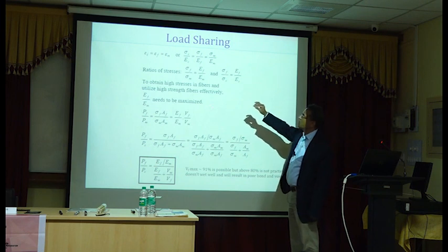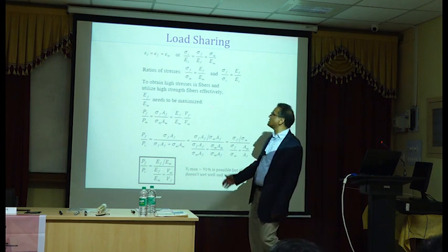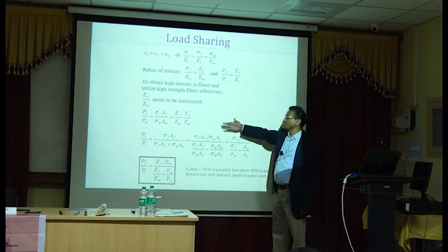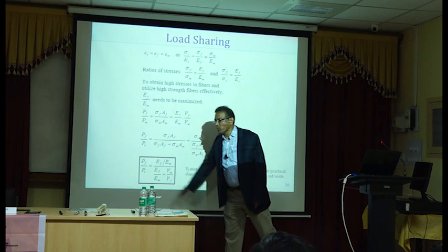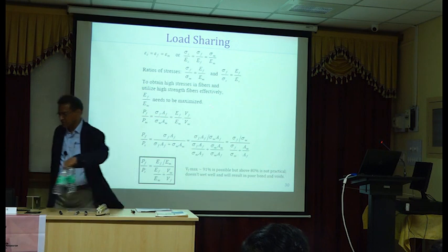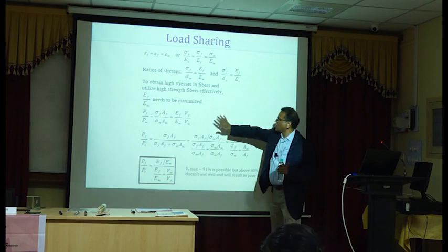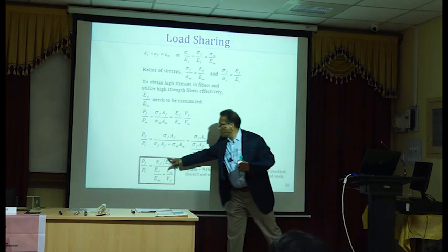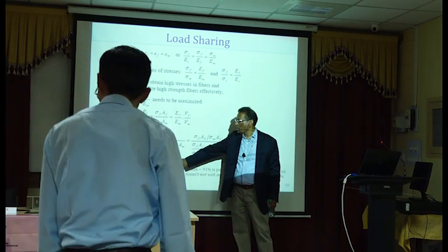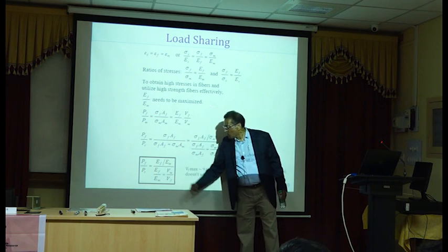Stress equals, or strain equals sigma over modulus. So that's what we have here. I will not go over all the lines because it's useless. You all know this so well. You teach all this stuff, so you really don't need me to remind you of this. But finally you'll see when I rearrange these terms, PF over PC will work out to be this equation here: PF over PC equals EF over EM over (EF over EM plus VM over VF).